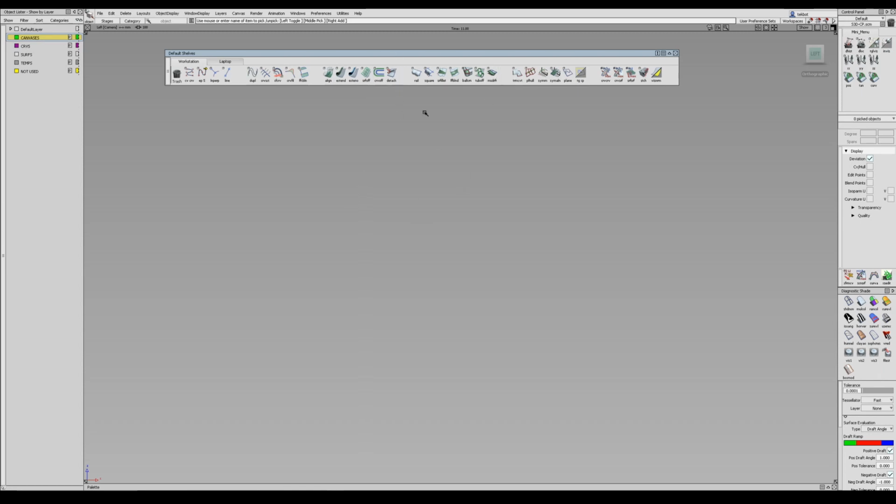The next group is all my surfacing tools. So rail and square, I use those interchangeably, but I try to use freeform blend whenever I can. I highly recommend some of the newer surfacing tools. I don't use these as often as I used to. And then surface fillet for any of the transitions. These probably should be organized more like this, but surface fillet and ball corner go somewhat hand in hand. Ball corner allows you to have a blended three-sided fillet intersection. That's a great tool.